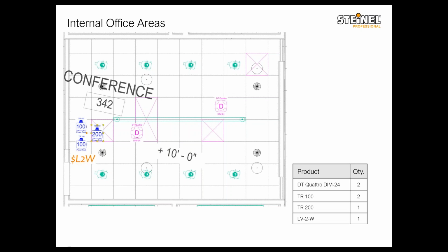So we need to have 2 lighting power packs, and of course we need a power pack for receptacle control. Same as our previous solution, you have the TR200 power pack for receptacle control, and TR100 power packs for lighting control. And then you have a 2-button momentary switch to provide manual control.